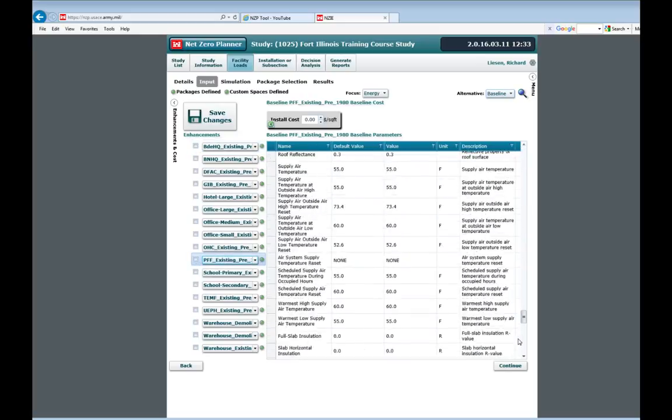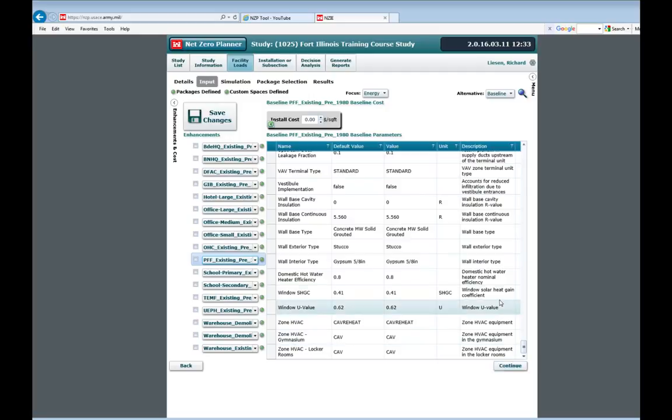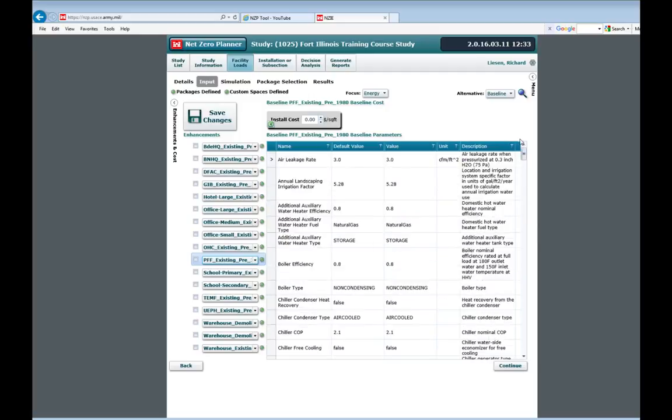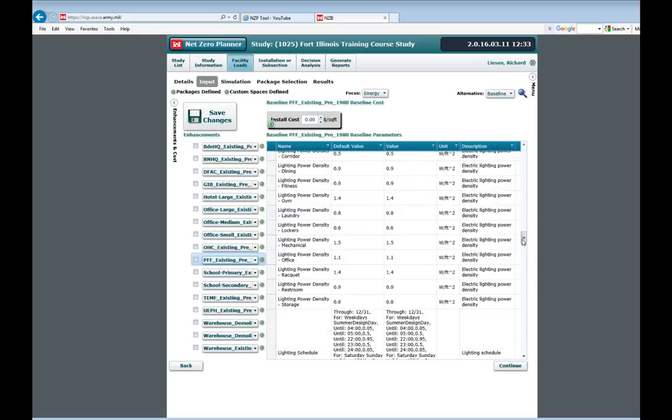So like I said, we can go through and look at all these different models to see if we've captured the envelope in the wall and exterior insulation. If we look at the air leakage rates, which has the envelope leakage plus the operation of the building, door closings, openings and closings, people going in and out of the building, it captures both of those for the simulation. Look at the equipment. Remember that the equipment here is just to give us an idea. Depending on what we do in the installation section, we get a different look at the equipment, and possibly we want to keep this in line with that from an individual contribution to that load. But the building does demand this at the coils and not at the machine level, so it's not demanding fuel, it's demanding heating and cooling when we go onto the installation section.